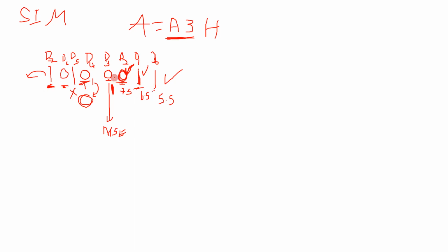So if you want to use the SIM instruction to deal with masking and unmasking the interrupts, this should be 1. So you should decide the respective bit pattern. Like I want to have AA. So when I convert this into binary, what will I get? This is the binary which I am going to get. This is D0, D1, D2, D3.